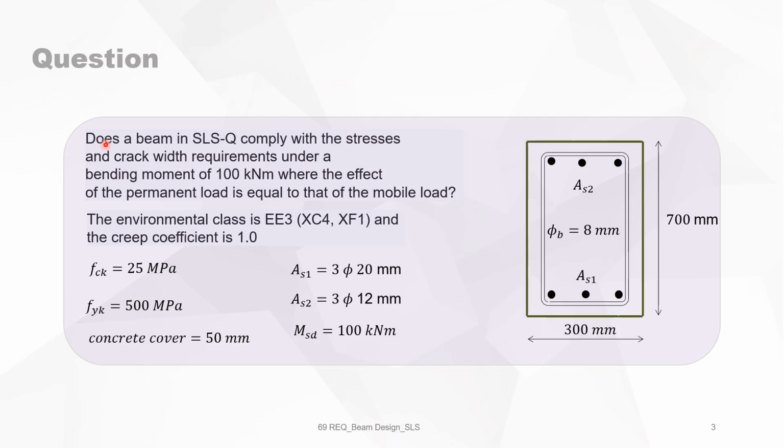Does a beam in serviceability limit state comply with the stresses and crack width requirements under a bending moment of 100 kilonewton meter, where the effect of the permanent load is equal to the effect of the mobile load?